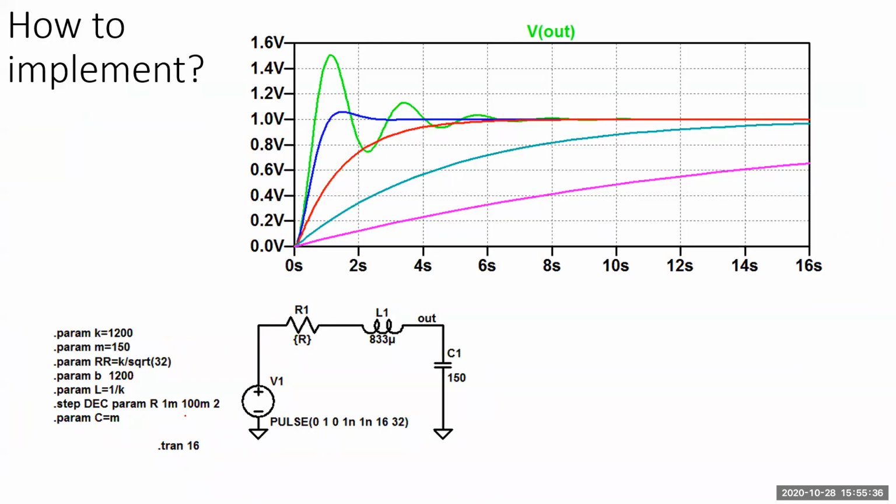And now think about it. What if I had the smallest R is a milli? Well, what if I put a nano, right? Right now it's taking 8 seconds to stop oscillating. So even though technically it's in control, can you imagine being on an elevator that goes up and down until it takes 8 seconds to settle before the door opens? So theoretically you're in control, but that's not really, in that context, a usable system.